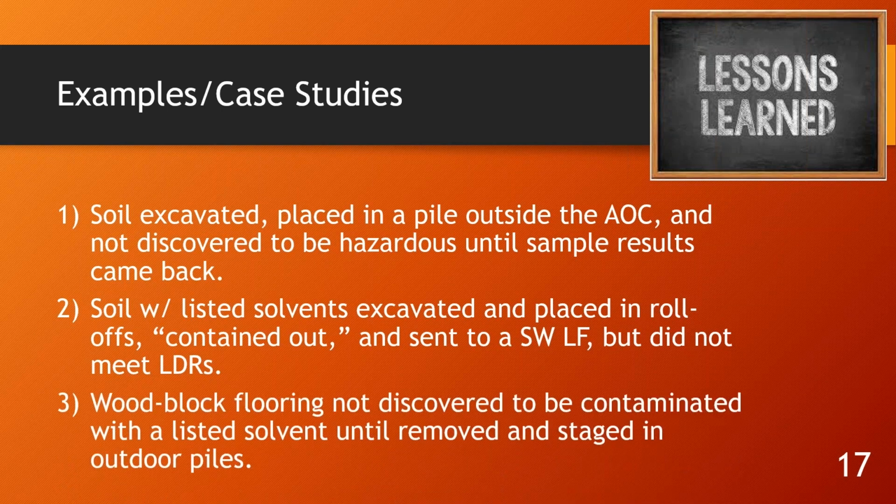Wood block flooring was not discovered to be contaminated with a listed solvent until it was removed and staged in outdoor piles. And this is another example of something that didn't seem like it was hazardous waste, but in accordance with the rules, really, if you're not sure, you should be cautious, treat it as a hazardous waste, containerize it in some way until you get your results back.